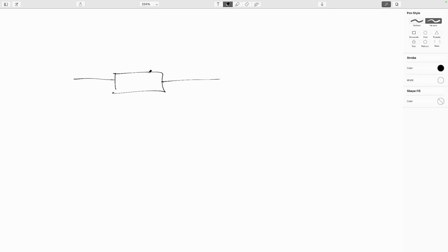They tend to look like little sort of ceramic colored cans that have some material inside. So we'll say this is a 10 ohm resistor, and I put a 100 volt potential difference across it, and I want to know what is the current flowing through it.